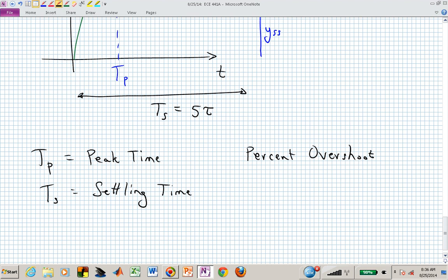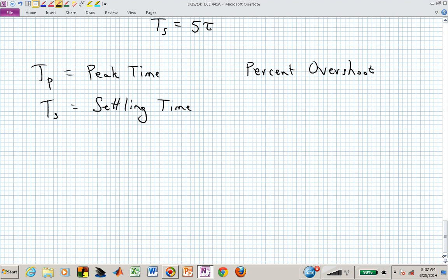If it rings a lot, we don't have a lot of damping, and we maybe have these poles very close to the imaginary axis relative to their, let's say, vertical distance. So they may be very close to the imaginary axis, and that might be causing them to oscillate, and they now maybe have more vertical distance than horizontal distance in the complex S-plane.